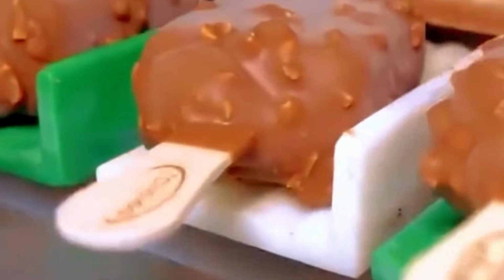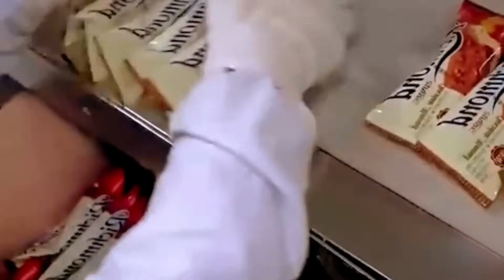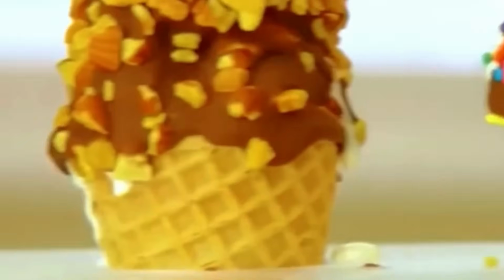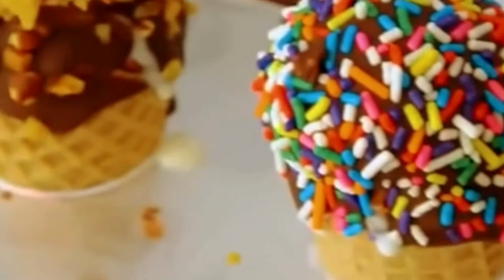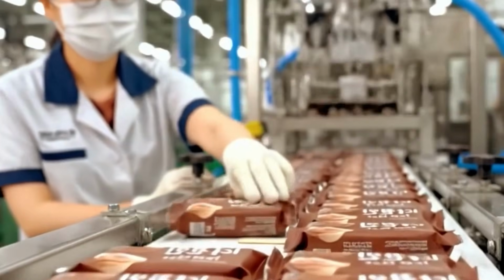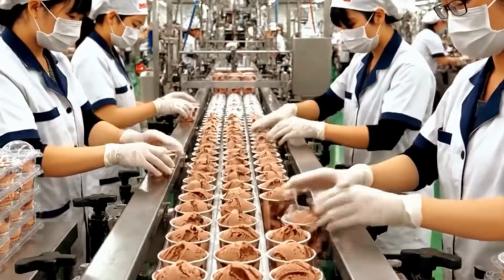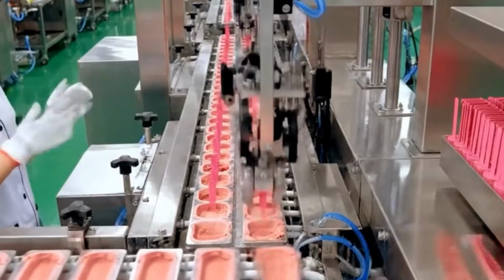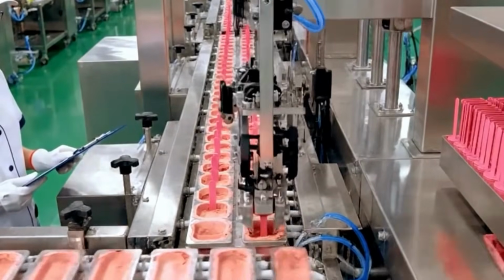The mixture is heated uniformly to 70-85 degrees Celsius using indirect steam in the jacket to fully dissolve solids and activate emulsification agents. This thermal processing step homogenizes the mixture and ensures complete dispersion of the fat phase. The hot mix is then passed through a homogenizer at pressures ranging from 1500 to 2500 psi. This high-pressure two-stage process reduces the size of fat globules, creating a stable emulsion and improving mouthfeel and overrun stability. Homogenization is measured and recorded by inline pressure transducers and flow meters.